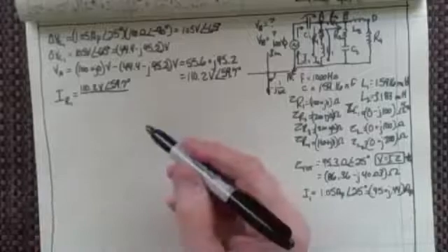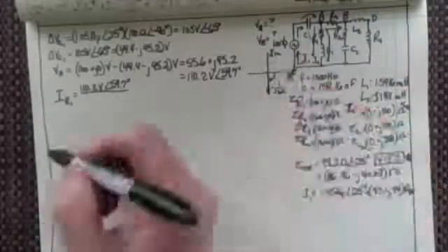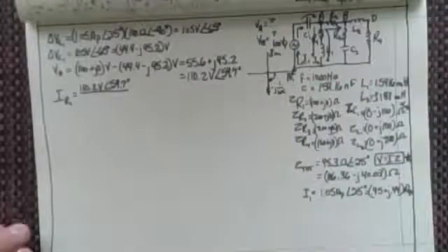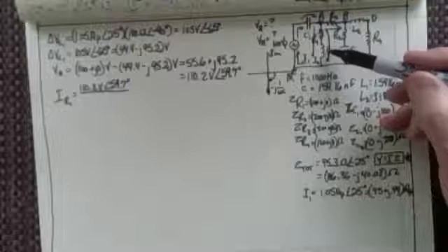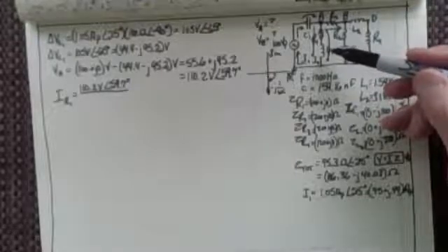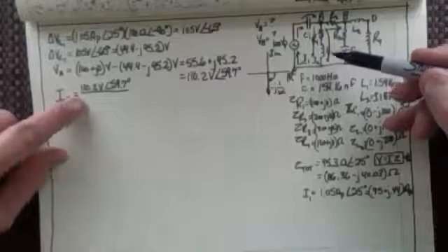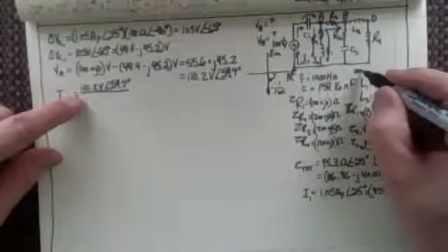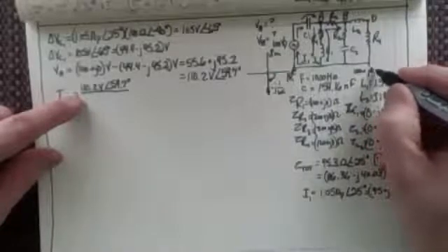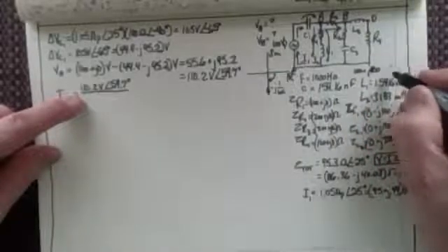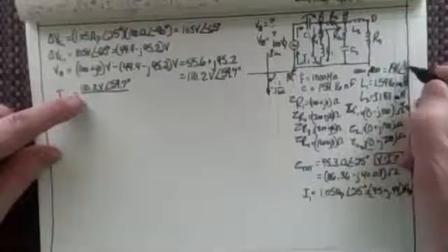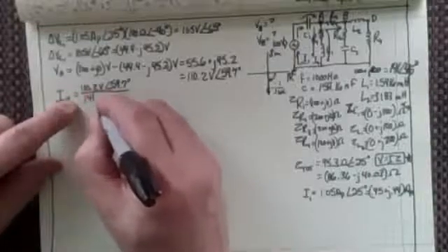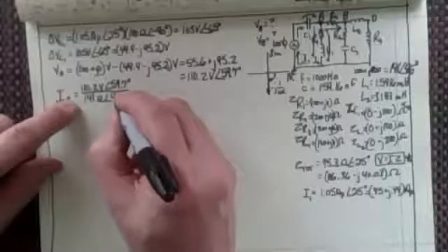And we know what the impedance of that is because it's 100 ohms for R, 100 ohms for L1. So it's just 100 plus J100, isn't it? I'll just write it here: 100 plus J100 equals 141 at an angle of 45 degrees. And so that's what we've got, 141 ohms at an angle of 45 degrees.